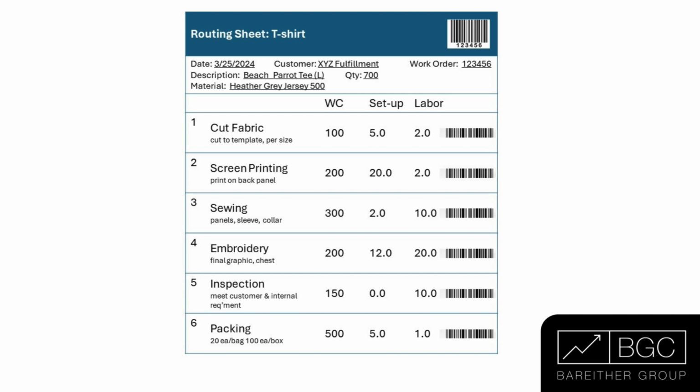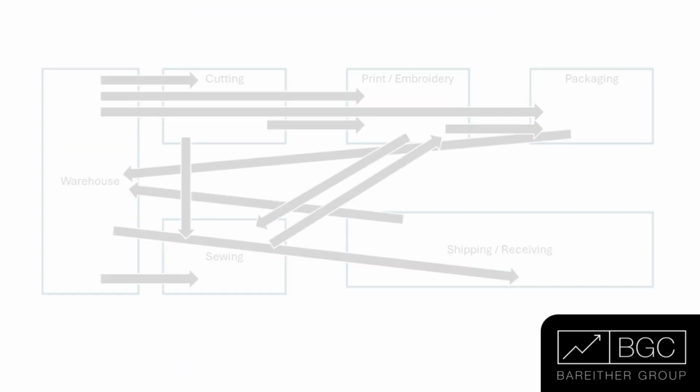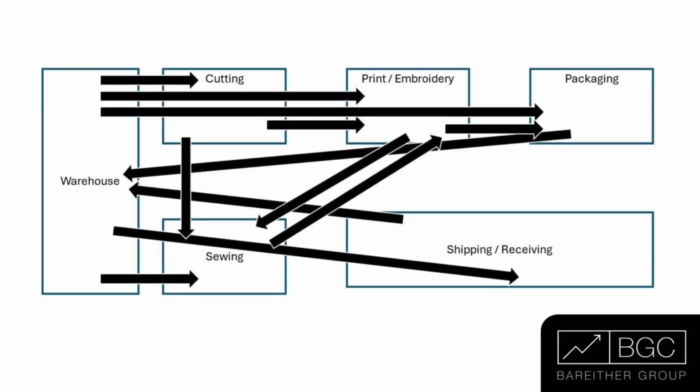But other things like the location of the work centers within the facility, the batch size actually determines the waste that you have in the process. So while the standard routing may follow those process steps logically, and it looks like it's streamlined, the costs that are not accounted for is the transportation waste and the overproduction in between process steps within that particular facility.